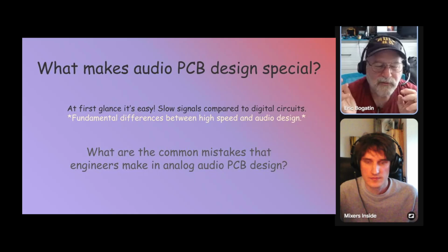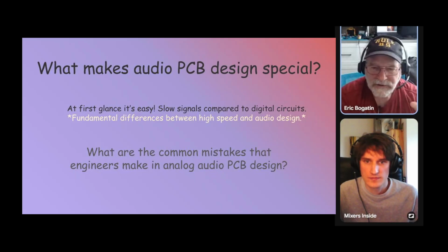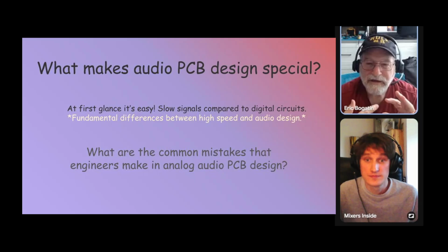We might care about 5% crosstalk in digital signals, but when you have a 1 volt signal that's the aggressor, and you're looking at a millivolt as the signal on the audio line, oh my gosh, that's 1,000 to 1, a tenth of a percent crosstalk between the digital and the analog.